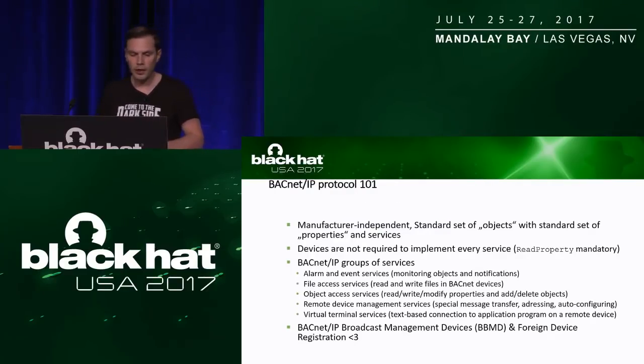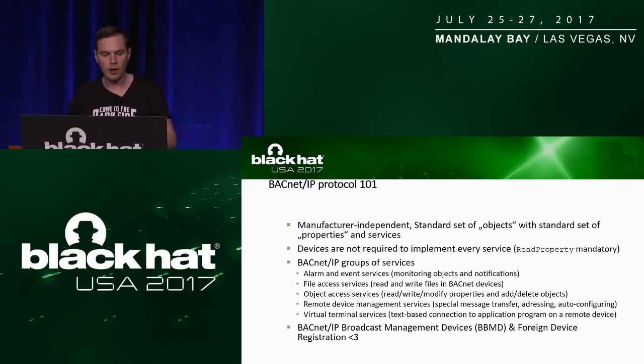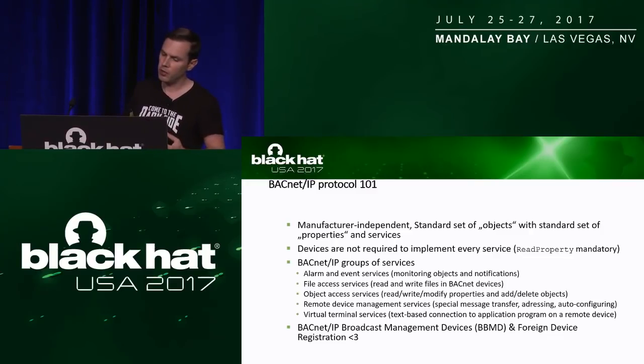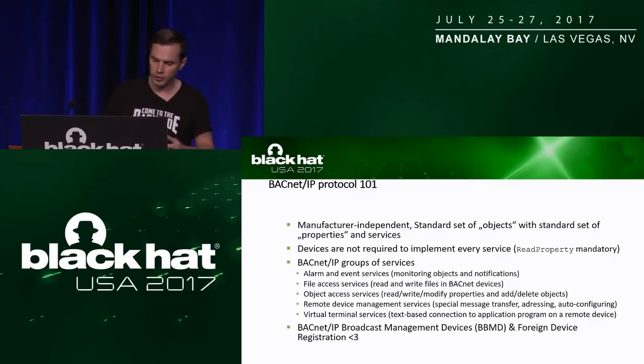Second protocol that I would like to explore with you is BACnet IP. I think BACnet IP is, especially for the US guys in the audience, much more interesting because it's widely used, especially in large-scale installations. BACnet is a manufacturer-independent standard, which means that you have a set of objects for each device with a standard set of properties and services. Some of those services are mandatory, like the read property service, others are not.